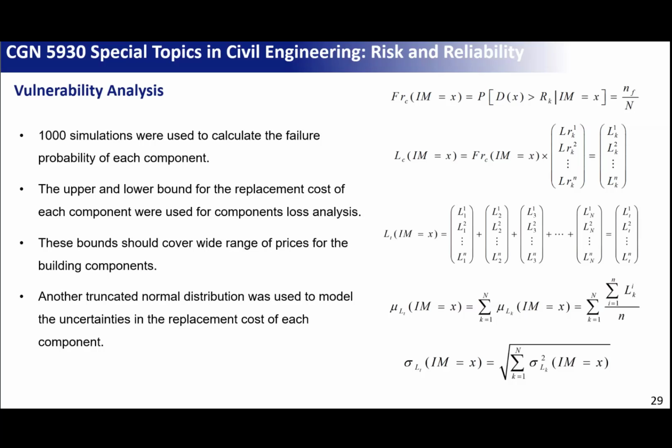If you have a ceiling, this one is not going to be damaged, so the losses for all these items will be zero, but this one is going to be damaged. This screen is going to be damaged. So you will have vectors that have lots of zeros and vectors that have lots of losses. And as the water goes up, you will have vectors that get filled with losses, right? And then we sum all of them and we get one vector at one flood depth.